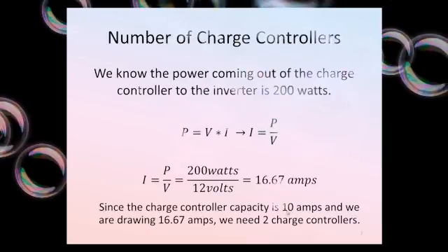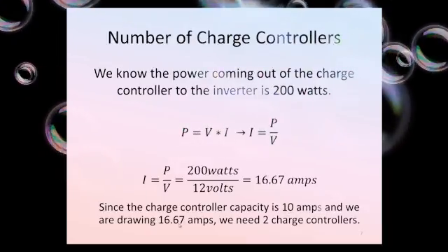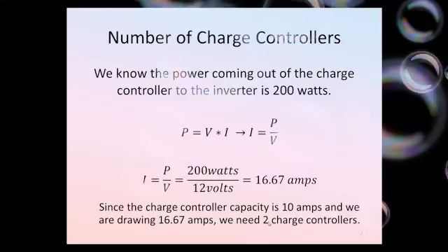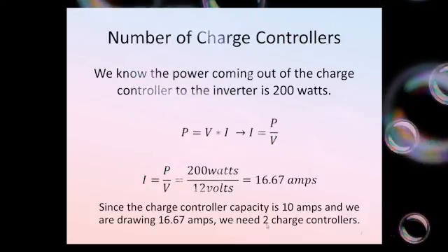Since our rating is 10 amps, and we're drawing 16.67, we need 2 charge controllers, because then our rating will be 20 amps for those 2 charge controllers.